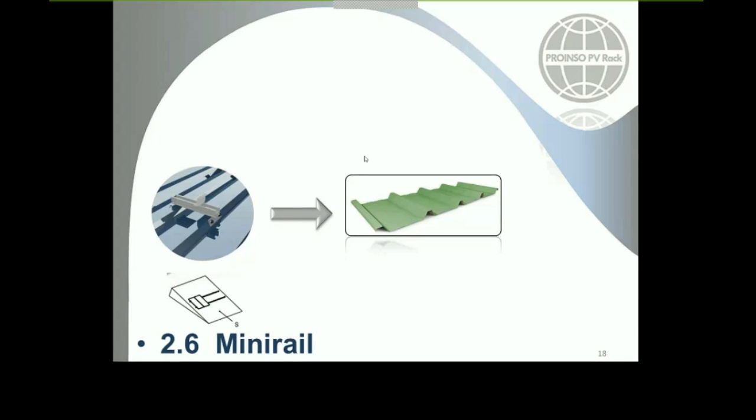It could be installed on any type of trapezoidal shape. That means if you have a different angle in the trapezoidal shape, or a different length, imagine that you are going to use the L connector, but there's not enough space in here. This kind of solution allows you to install whatever the shape of the trapezoidal sheet, because it can be adapted.